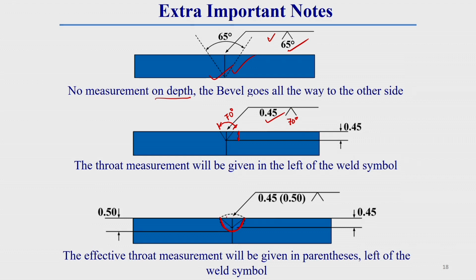After welding that, whatever depth of fusion we are getting, that means from here to here, is the depth of fusion. Once we do the welding, some of the base material is also fused or melted, this extra base material. So generally the depth of fusion is considered up to the top of these two fusion depths. This is generally called depth of fusion.